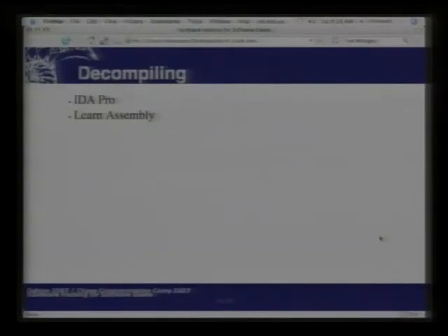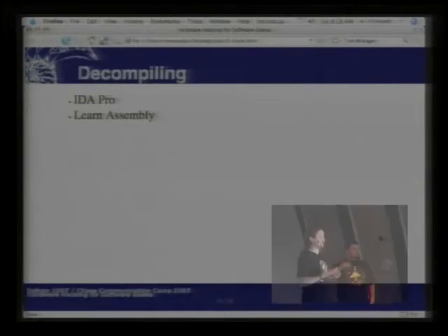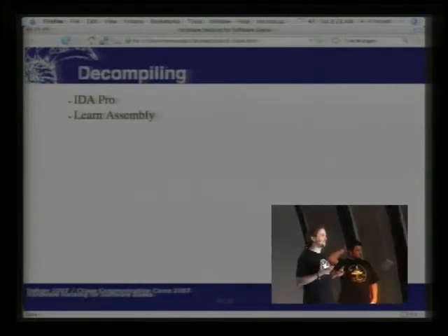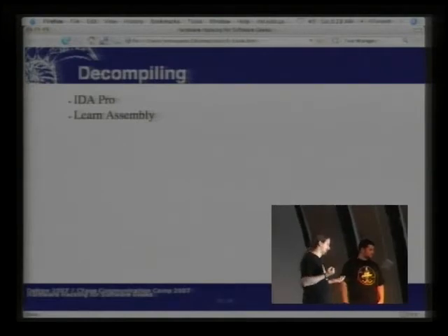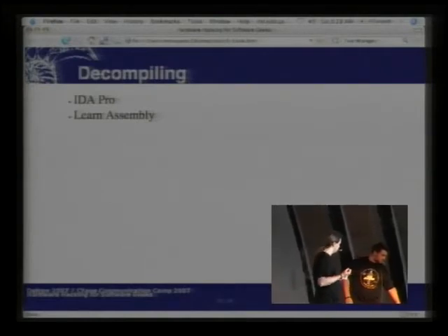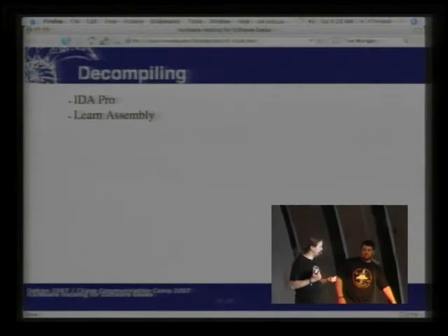Once you have the data sheet, you can teach yourself the assembly language. And once you learn one assembly language, the majority of assembly languages are, to some degree, similar. You'll end up with the typical push, pop instructions. In Motorola assembly language, interestingly enough, the pop instruction is not pop, it's pull. The opposite of pushing something onto the stack would obviously be pulling it off, not popping it off, which is an interesting design decision on their part.